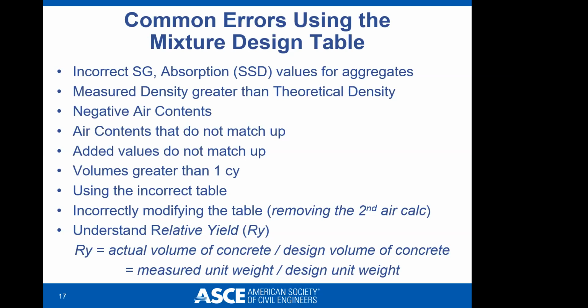It's not 100 pounds for whatever reason. And you do enough to sit there and say, I can reproduce this over and over again. At that point, you're like, okay, I need to adjust the values of my mix design. So it is a ratio. So if I had, say, a 103 pounds per cubic foot mix, but I thought it was going to be 100 pounds per cubic foot, you actually made a denser mix.